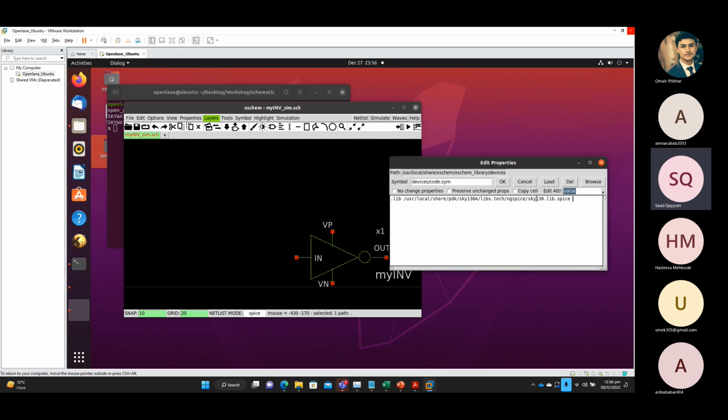And when you fabricate the device, it would have a distribution of properties. So it's normally distributed with some typical values and some fast values and some slow values. So generally, we would like to simulate a circuit for a typical implementation. So when you fabricate the chip, it has a distribution of properties with a normal distribution. So what we do is we type TT, TT telling us that it is a typical corner. So most of the devices fabricated would be lying inside this process corner.